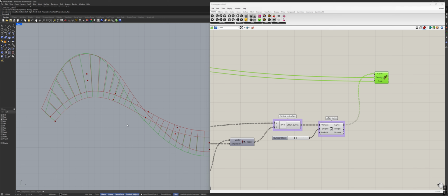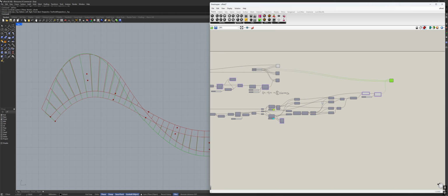As you can see, none of them are actually ideal. Every one of them forces you to sacrifice something. If we're talking about the automatic method, it sacrifices the quality of the curve or the surface, when we talk about surfaces. And when you're using a CV offset, it sacrifices the distance and the continuity for the quality of these segments. Okay, so now let's get back to Alias.